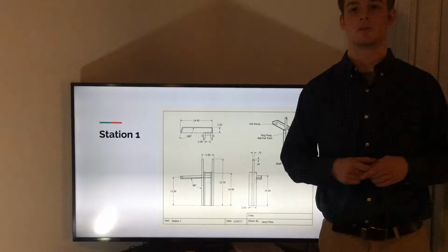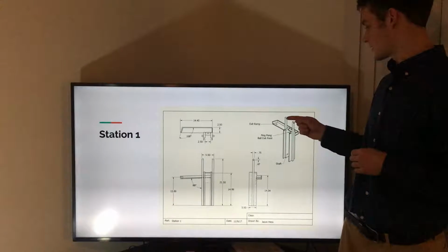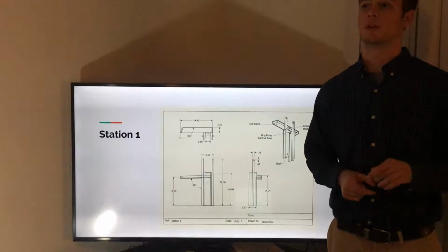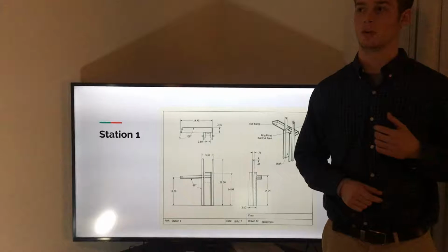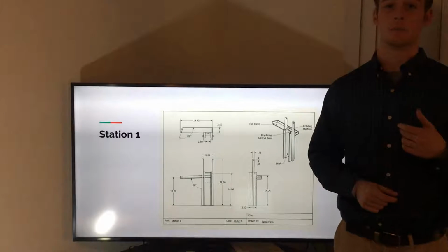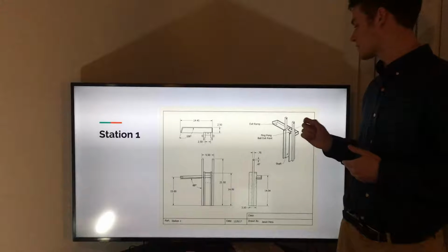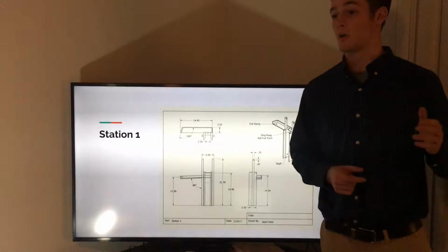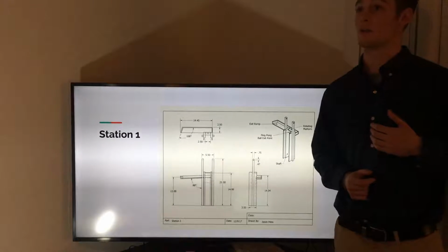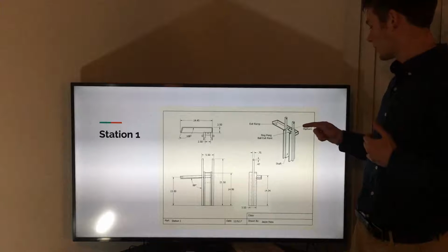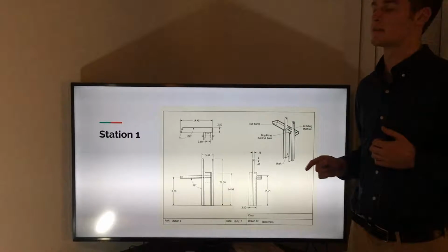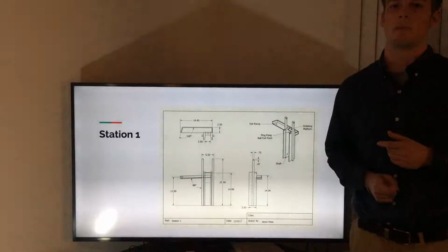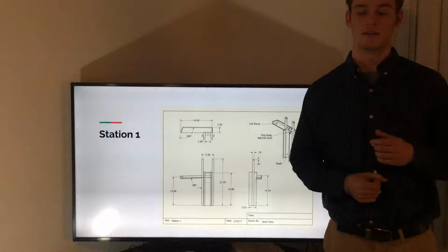The elevator cart is attached to a spring which drapes over a pulley that sits at the top here and attaches to an Arduino servo at the other end. The user inputs some computer code, which causes the Arduino servo to start rotating and winds up the elevator, causing the cart to rise. When it gets to this point of elevation, the ping pong ball exit point, the ping pong ball exits the shaft, but the elevator itself keeps rising, and it hits the bottom of this rotating platform on which a marble sits. It causes the platform to rotate and the marble to fall off and onto the same path that the ping pong ball is taking, which leads to the second station.